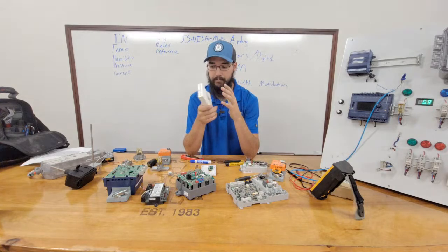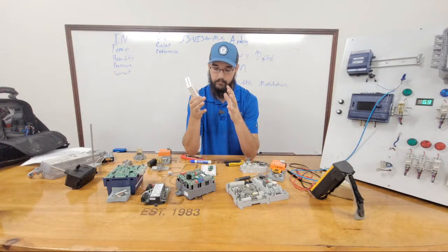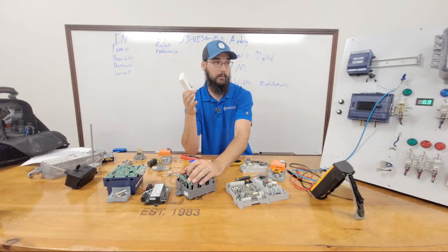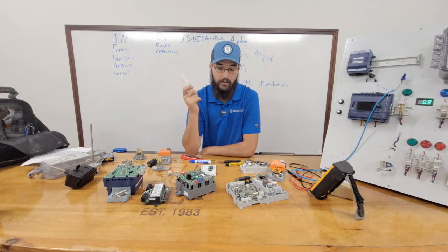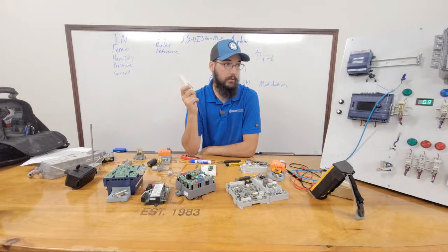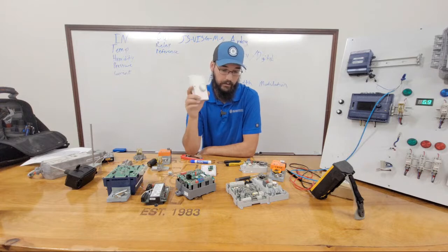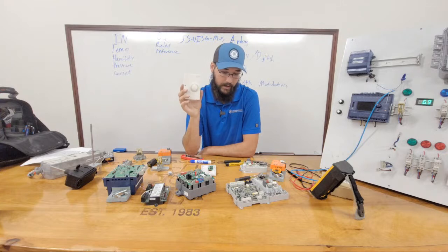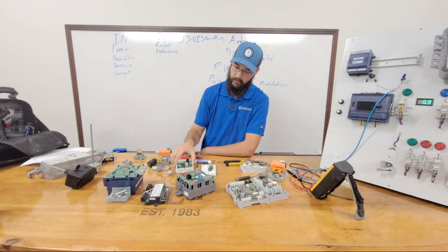Or it could be just the input on here. Maybe it's not logic, maybe it's not anything else. It's just where the cable plugs in just isn't good anymore. The physical input has failed. So ultimately, if they did read different, so say you did the swap and the new one read properly, then yeah, obviously change out the wall sensor and you're good to go.